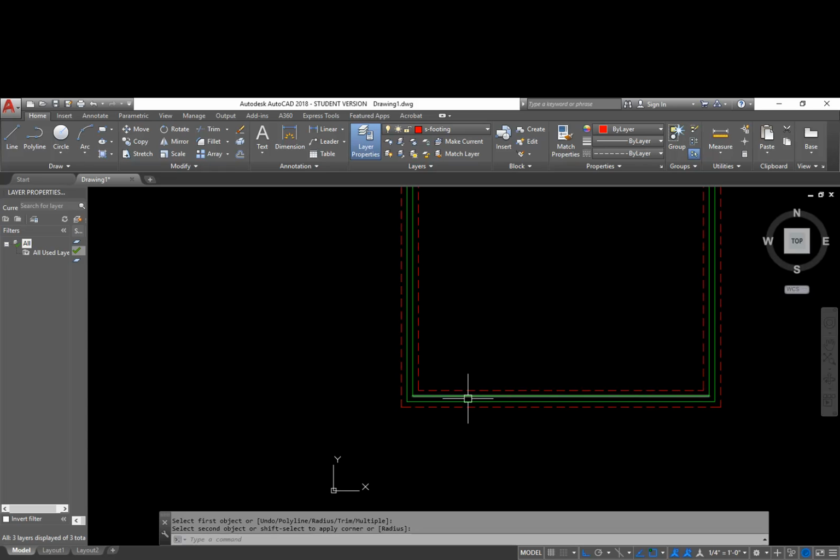The next step would be to go through and figure out if and where any openings would be in my foundation wall. Our design criteria said that these foundation walls are going to come up 8 inches above grade level. So whenever I draw these, that means that my overhead door openings and my man door openings are going to cut into, or recess down into, that top layer of CMUs, down one course of block, so that my door can open up onto my slab, as opposed to having an 8-inch step down from there.